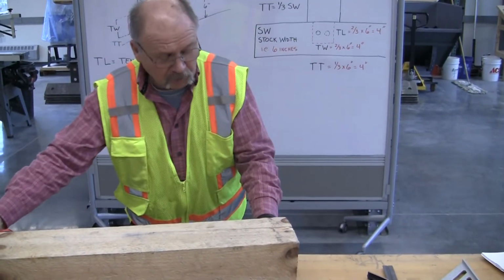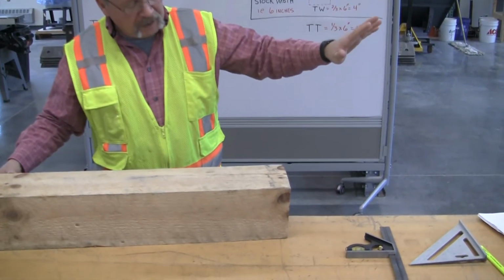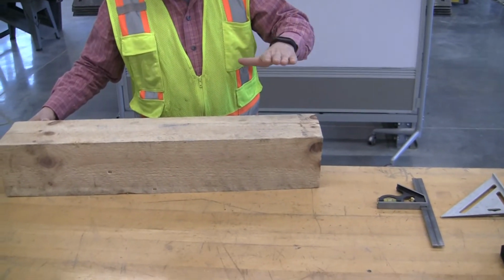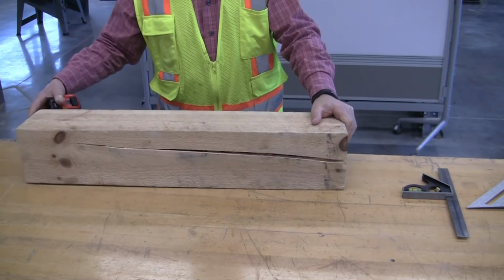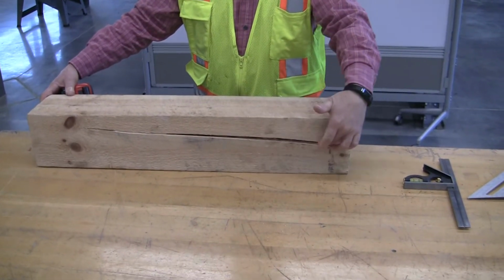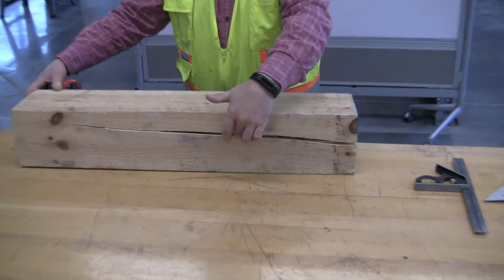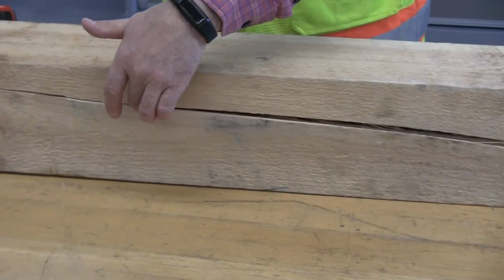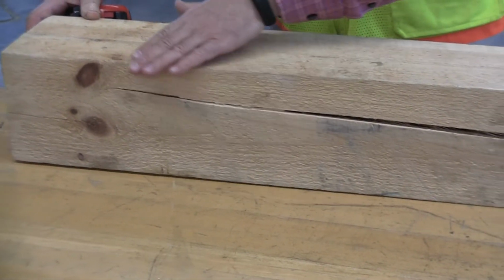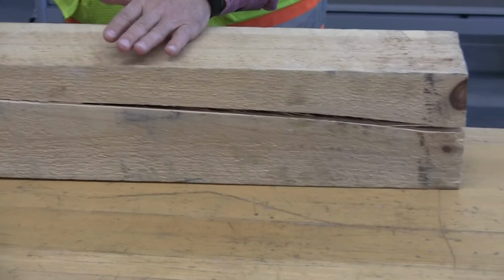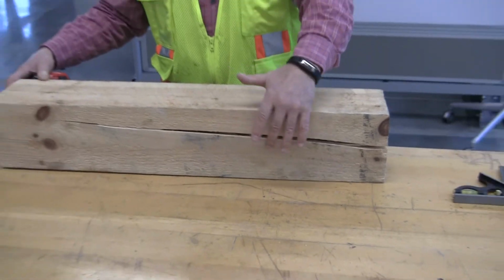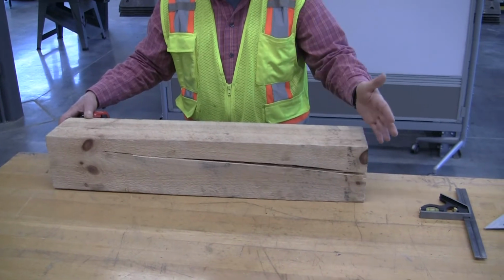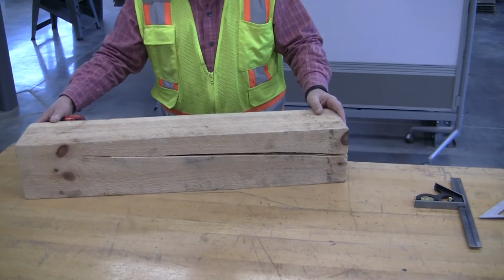Now earlier we talked about the lumber that we have over on the rack as being relatively green, actually very green, and over time, this is what I would consider to be a severe check in the lumber. And this is normal for wood that is being used in timber frame construction. Still structurally very sound. Some of the cracks do get severe enough that we may have to do some patchwork over time. But with that being said, I'm going to give you an idea.